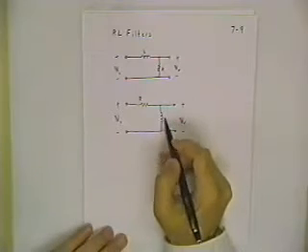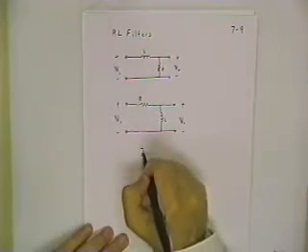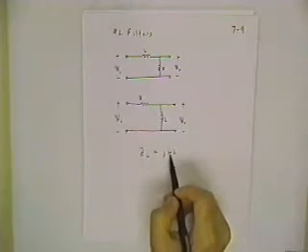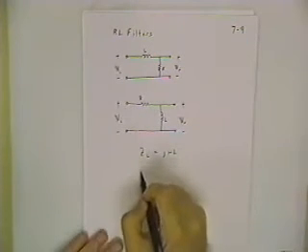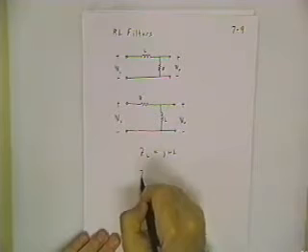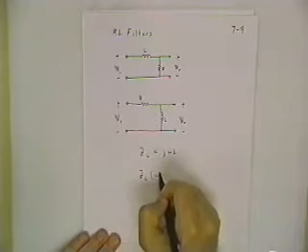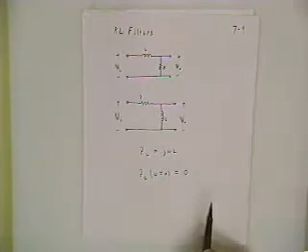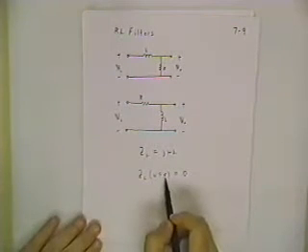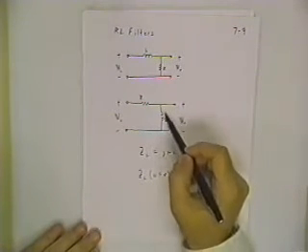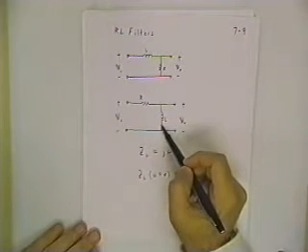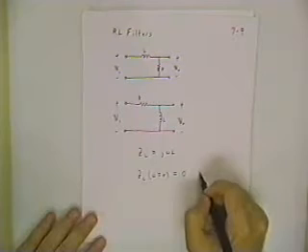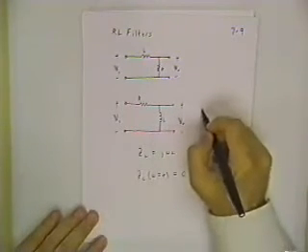What you do is you look at the impedance model for the inductor, and you say Z sub L is directly proportional to frequency. So Z sub L for omega equals 0 is going to be equal to 0. And that means at low frequency I have 0 impedance across this inductor, so I get no output. So low frequency, no output.